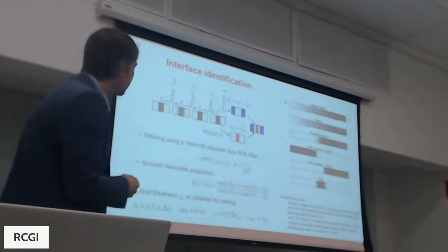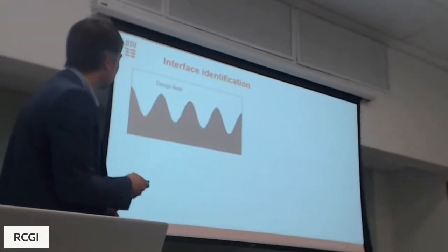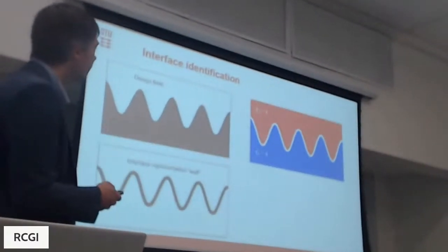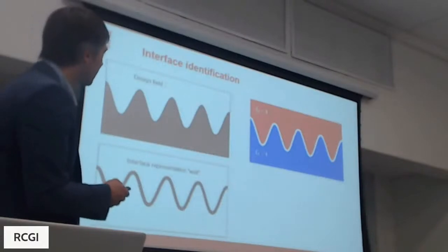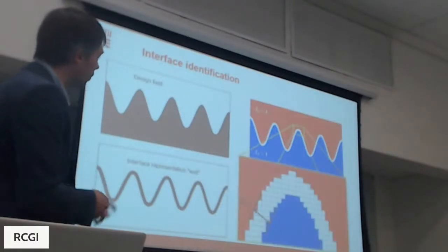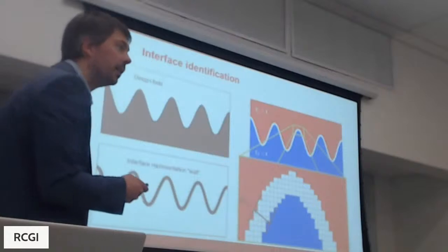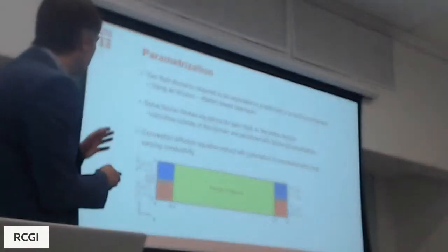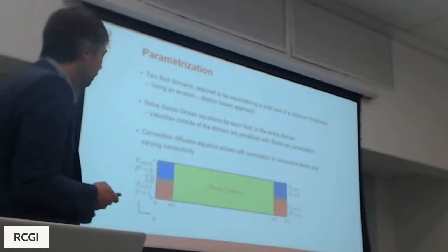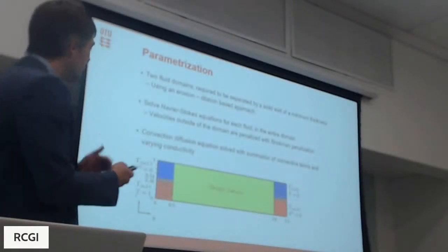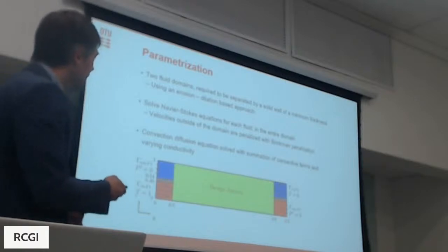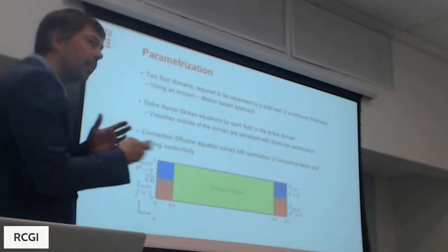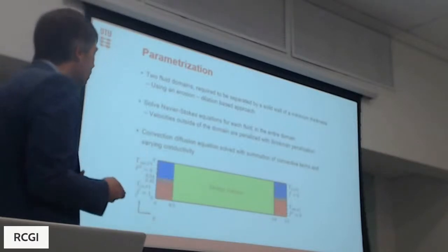So, yeah. That means basically this would be the design field. We make an interface representation of this wall, and then we subtract the two and see that we have two different phases here, side 1 and 2, and then we can actually prescribe the wall thickness here in between, so we can have multiple elements with thickness. So the real question is, can we optimize the heat transfer in this counterflow heat exchanger? For instance, or it could also be the shell and tube heat exchanger here shown. So we are interested in how much enthalpy we transfer from one side to the other.